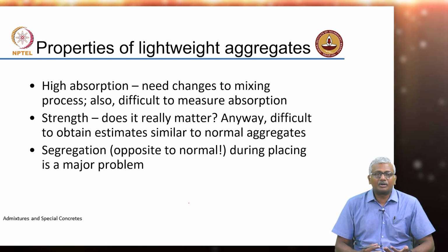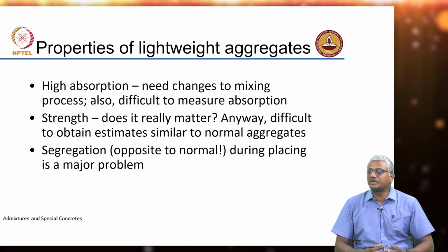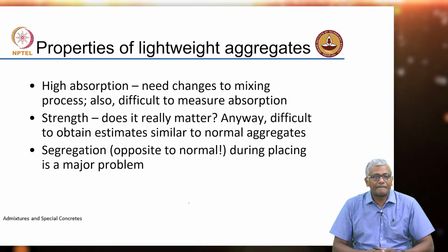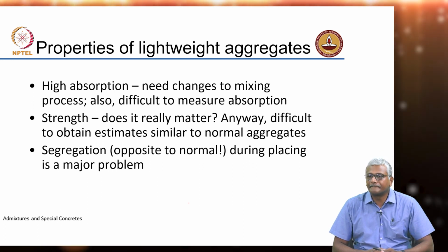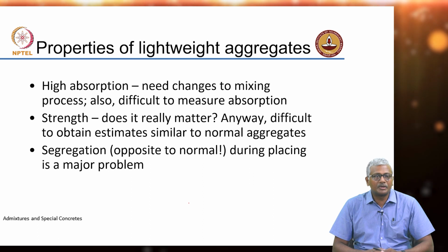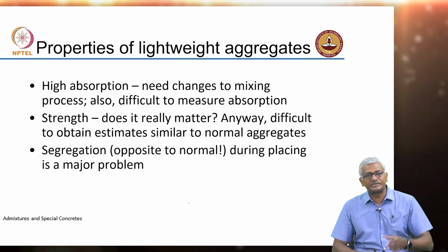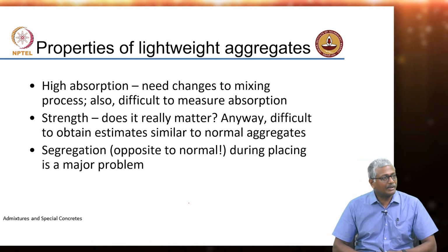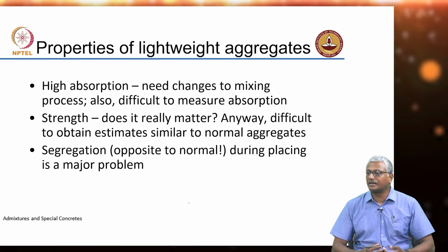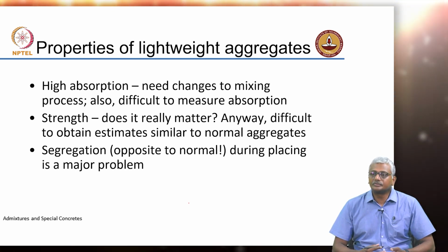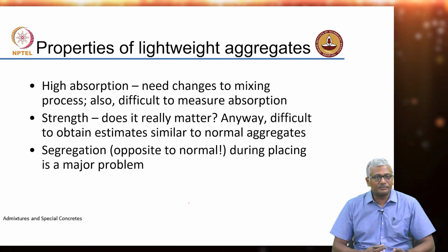Now, strength of the aggregate, how do you determine strength of an aggregate? What kind of experiment do you do? You do the impact and the crushing test, right? Essentially, you take a sample of the aggregate and you have this hammer that drops, and then you measure how much of the aggregate is still retained beyond a certain size, right? So, that is the strength of the aggregate.